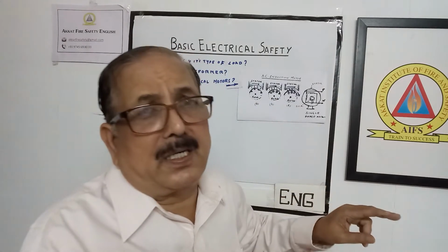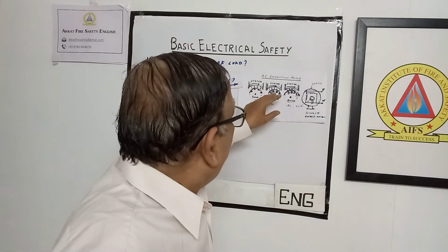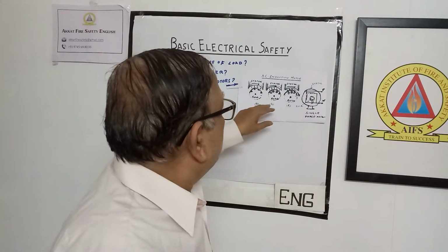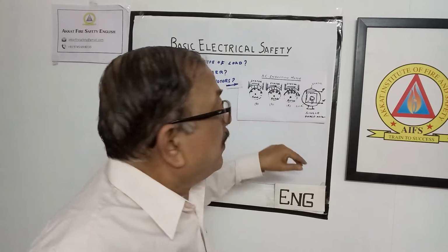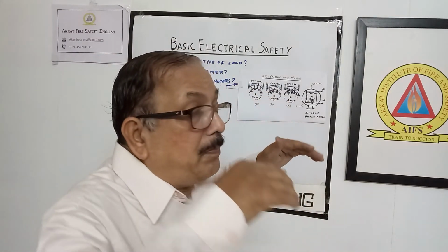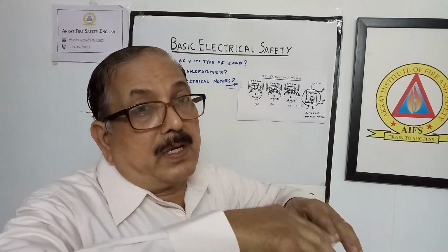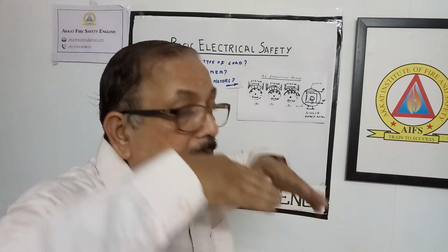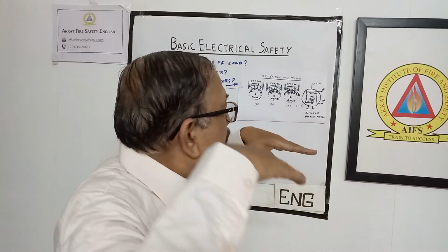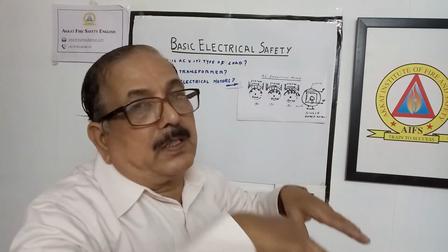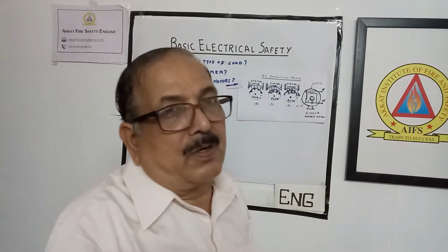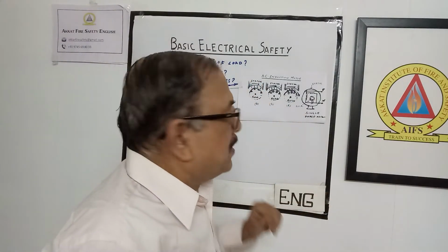This is just like a shorted secondary of a transformer. Because of that induced current, some magnetic field is produced surrounding the rotor conductor. Now what will happen? The main flux is coming this way, and there is a rotating magnetic field. Now this will be pushing the rotor. The stator flux starts pushing this rotor, so that the rotor starts rotating. So this is the basic principle.